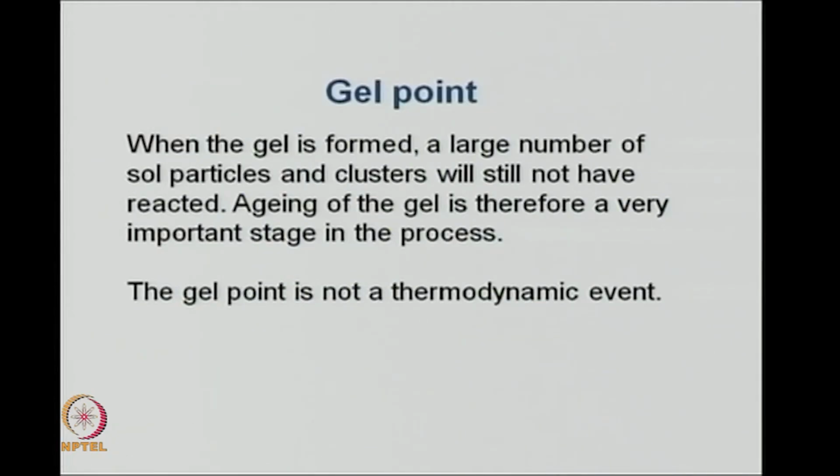So, the gel point is a point where a large number of sol particles and clusters still have not reacted. The aging of the gel is therefore a very important stage. Although from sol to gel you have a transition, the gel point is not a thermodynamic event. You have to age the gel because there are still more sol particles there and more clusters have to take part.